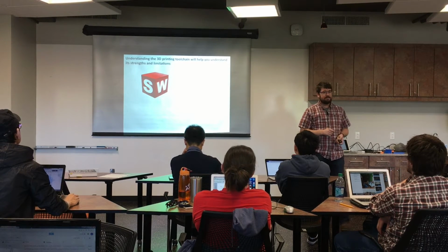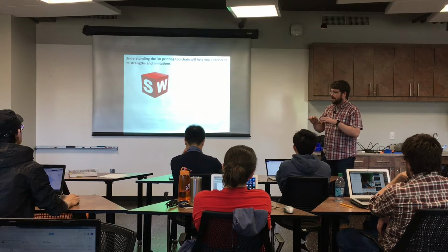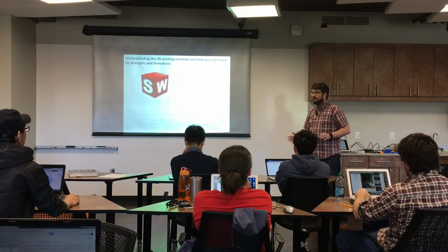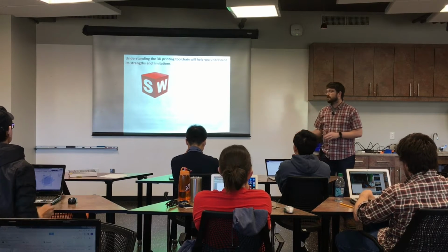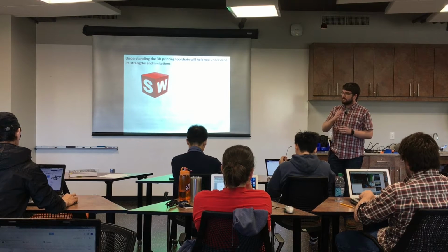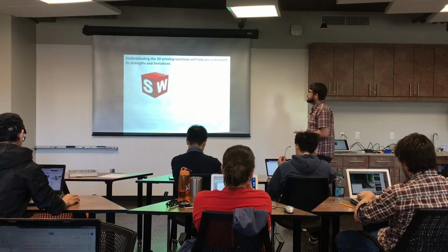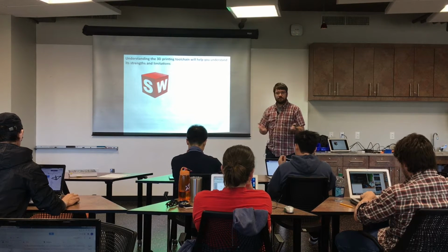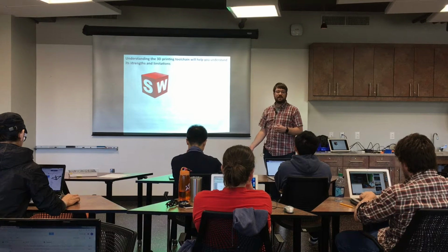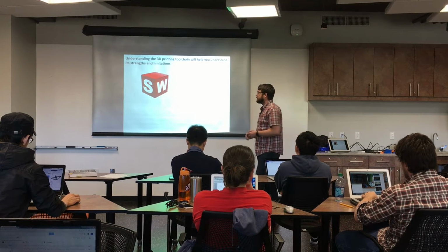Understanding the tool chain of how a 3D printer works is going to be pretty important, so you know how to go from the CAD file that you design to the 3D print. Some of these steps will be taken care of for you if you use the library. I'll tell you what those are, but it's helpful to know what's going to happen to your design because that can help you figure out where things could go wrong, and they will. Also, if you design it in millimeters and that's not specified when you send the file off and they interpret it as inches, things can get bad pretty quickly.